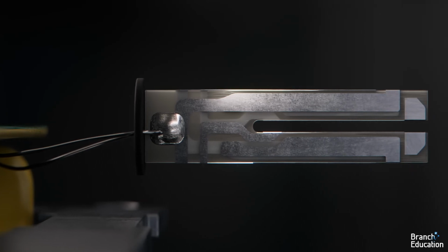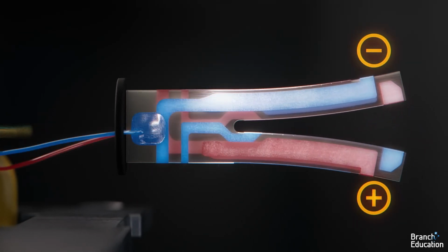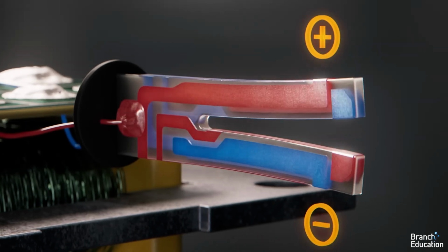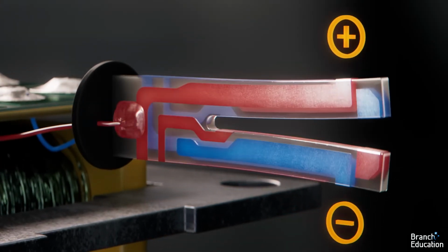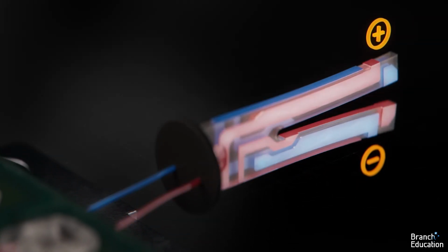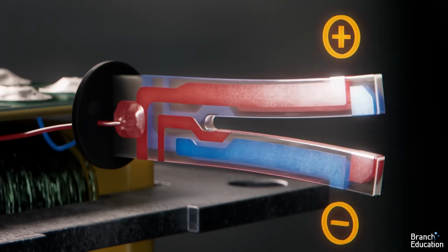As mentioned before, when a voltage is applied, the tuning fork lengthens and bends outward, and when the voltage is turned off, the quartz bounces backwards. The crystal bounces back and forth, creating positive and negative voltages, with the frequency of oscillation being dependent on the orientation of the crystal lattice, as well as the shape and dimension of the cut crystal.